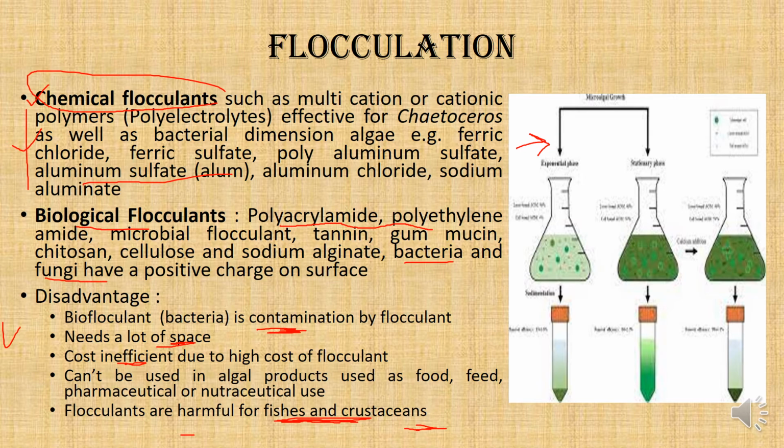And one thing I forgot to mention in flocculation is that when the flocculants are added to the solution, we usually add flocculant with gradual stirring. This is a very little amount of speed, that is 20 to 30 rpm, a very slight rotation of a rotor.